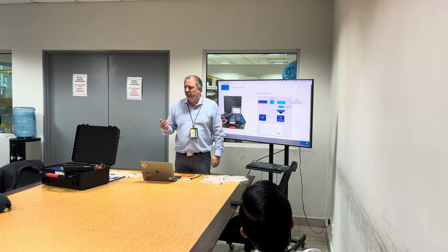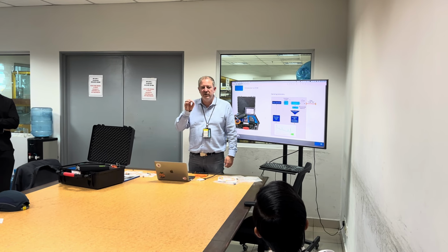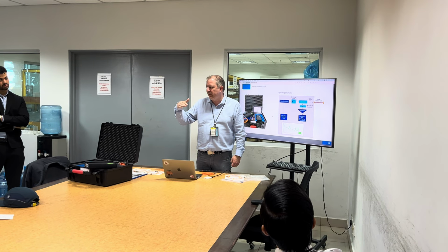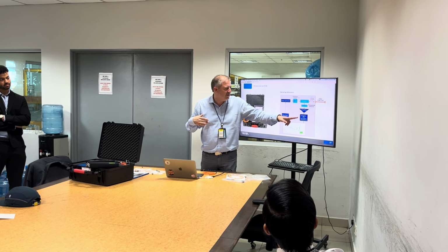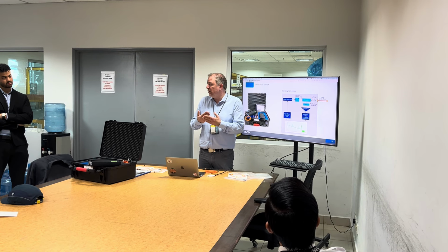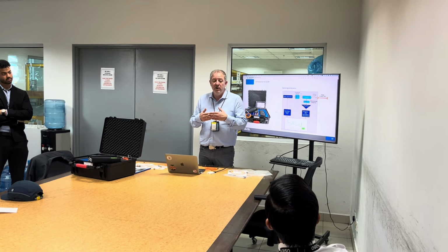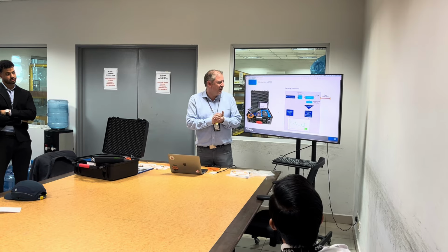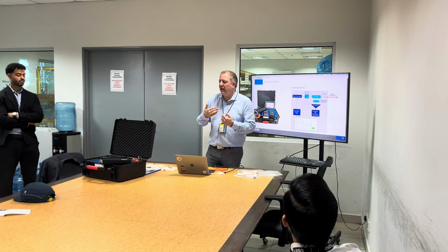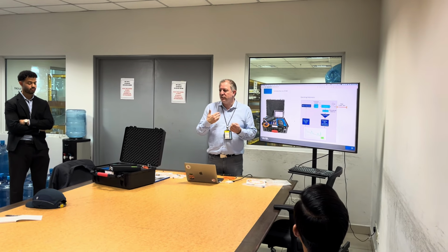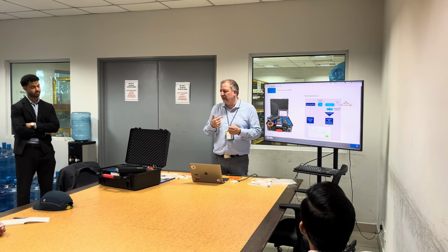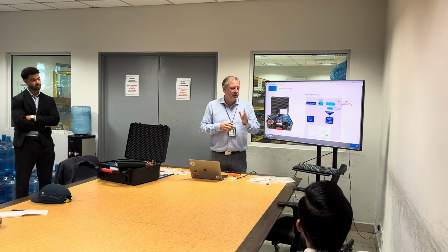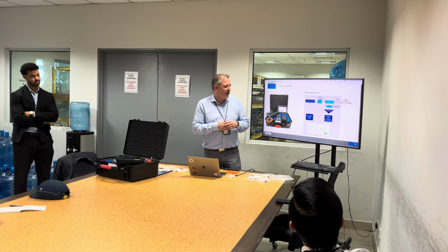Most of the time we use photon counting, so it's a very low level of light that is collected by the system, because on a typical fiber optic you have very low backscattered light, so light which is coming back naturally. You always have some photons, but very few that are coming back in the fiber.